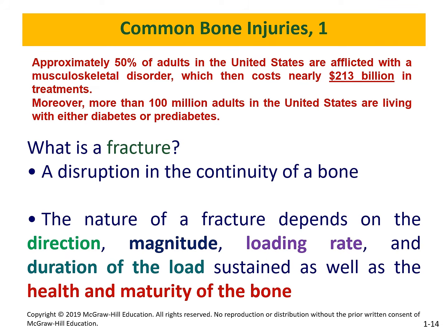So force divided by area is stress. The ultimate strength is actually that point, the stress that is, after which we have a fracture of the bone. Having this strength is one factor. There's another factor for fracture, which is a specific direction. So we have a magnitude, exceeding the ultimate strength, and a specific direction, because bone, if you're